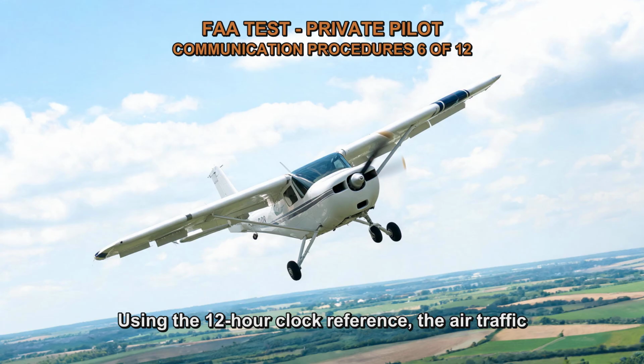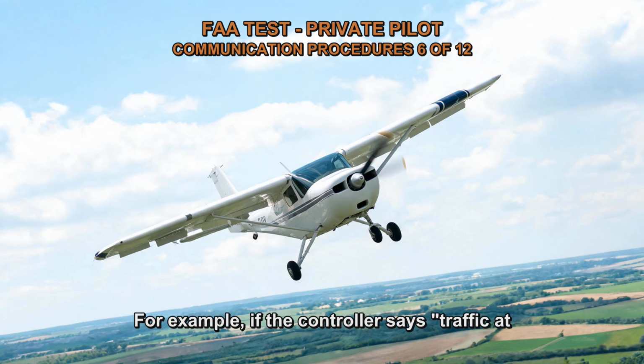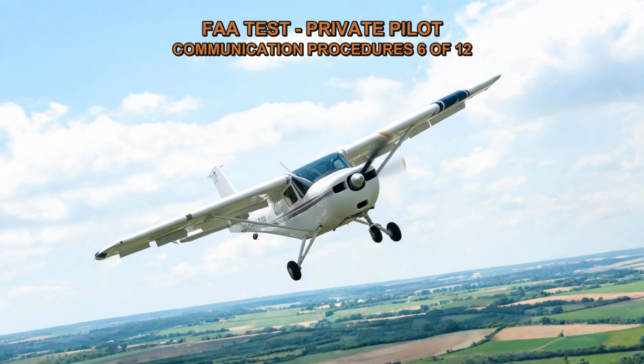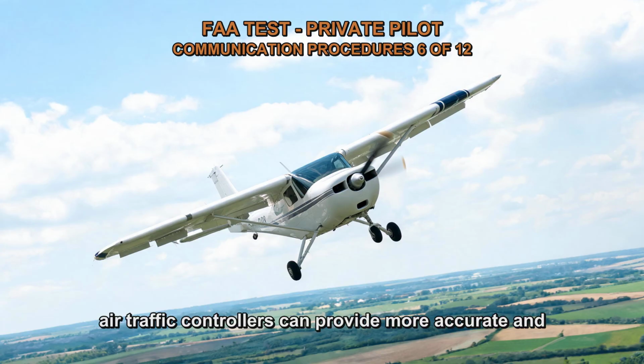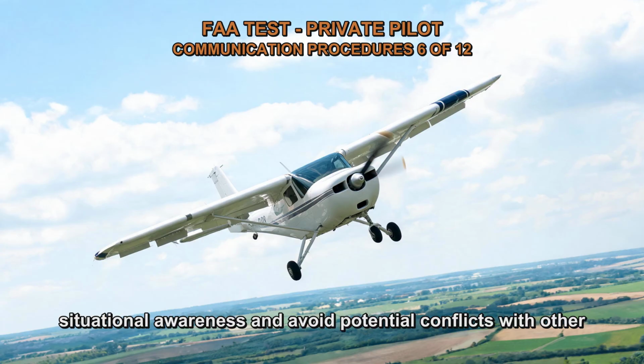Using the 12-hour clock reference, the air traffic controller will provide traffic information in terms of the direction relative to the aircraft's ground track. For example, if the controller says traffic at 9 o'clock, it means the traffic is to the left of the aircraft's ground track. Similarly, traffic at 3 o'clock means the traffic is to the right of the aircraft's ground track. By using ground track as the reference point, air traffic controllers can provide more accurate and relevant traffic information to pilots, helping them maintain situational awareness and avoid potential conflicts with other aircraft.